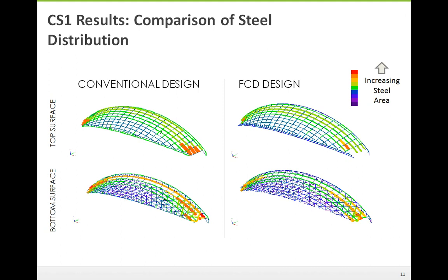So this makes it more efficient by making it stiffer further back where the cross-sectional area is the deepest. You also avoid, if you look at the conventional design, quite a lot of steel on the supports. You see a lot of orange, and that's because the structure was deflecting under the loads and it's fixed into concrete on those 2 supports on each side of the arch.